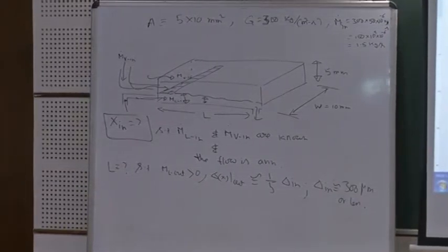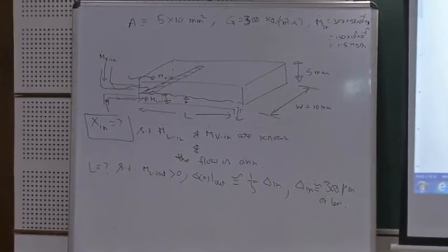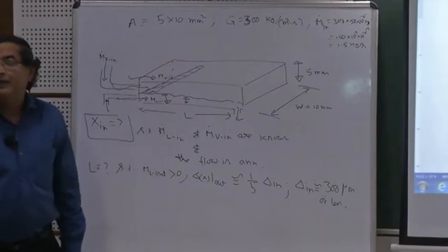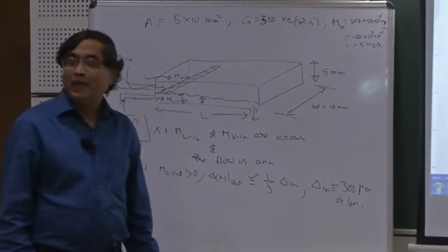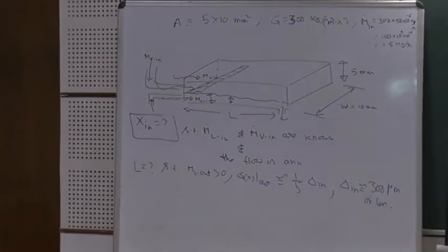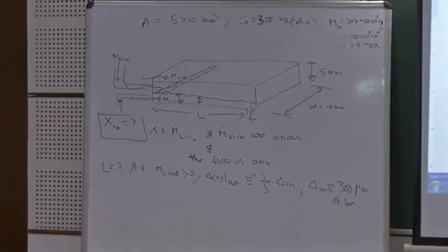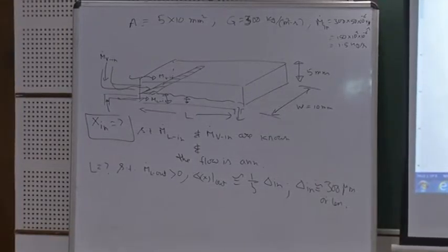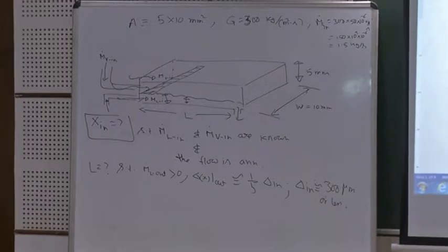But if the goal is to cool some device at a certain heat flux, certain heat load, and that it be energy efficient, then what is important to be micron and submicron scale is the liquid, not the cross section of the tube, if you can help it. Those are the constraints. That's the reason for doing these problems at millimeter scale, which is neither too big nor too small.